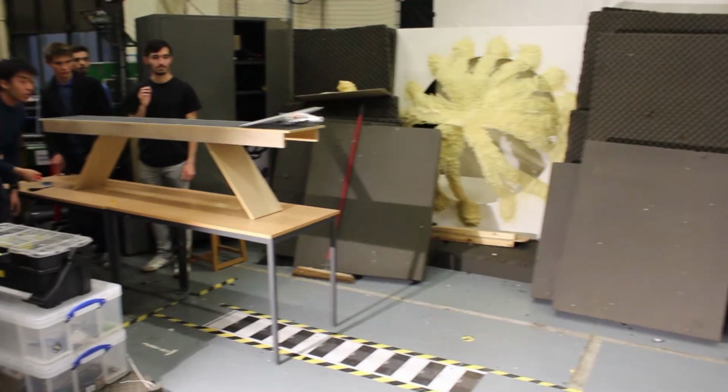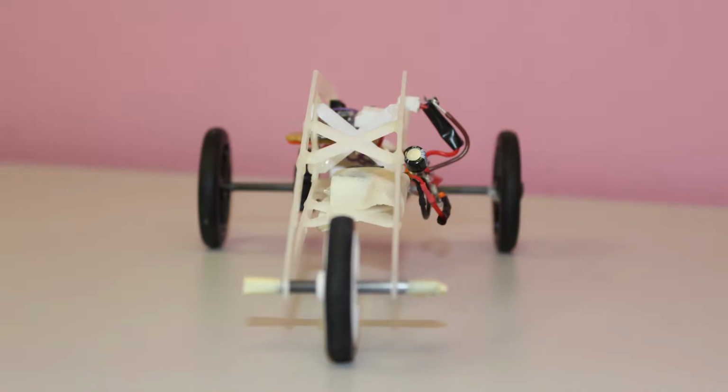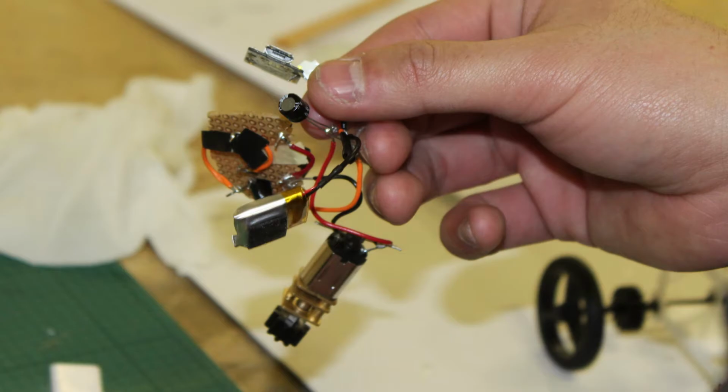In one of the tests, the glider's slight CG bias to its port side was evident as it would veer to the left during flight. This could be solved by designing a cage for electrical components to sit in, thus centralising weight components. This would also involve a reorganisation of our circuitry into a more compact form.